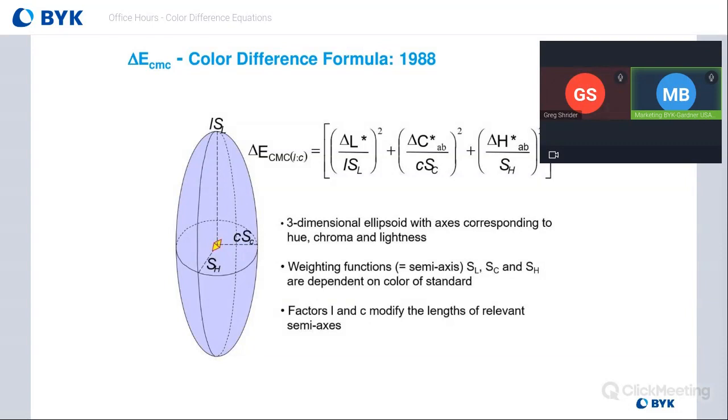Okay. So I guess let's continue down some of these questions. Anna had asked what was the best way to measure color of non-woven fabric materials. Non-woven fabric materials is probably going to be best measured with a sphere instrument.